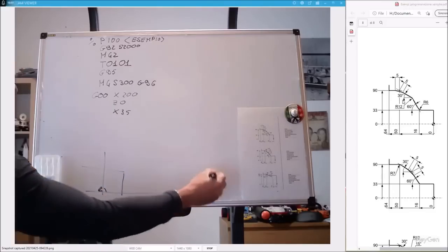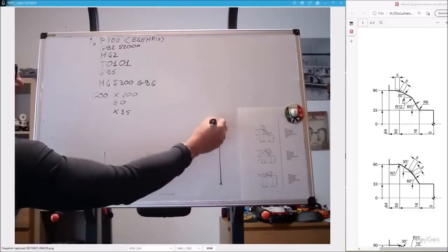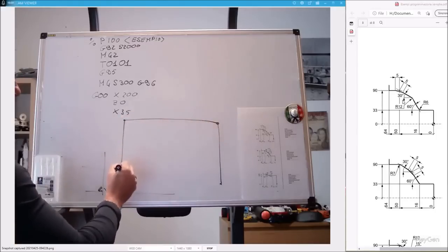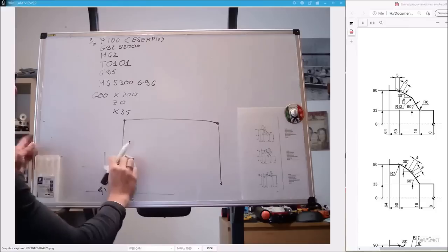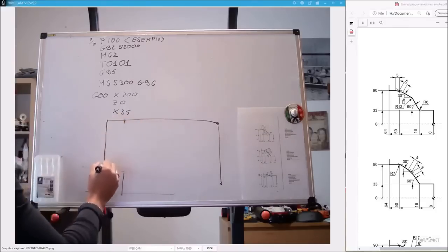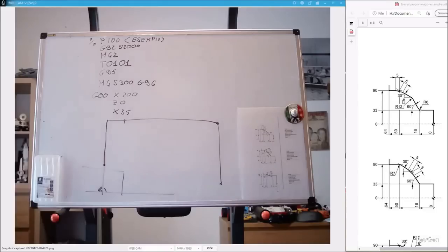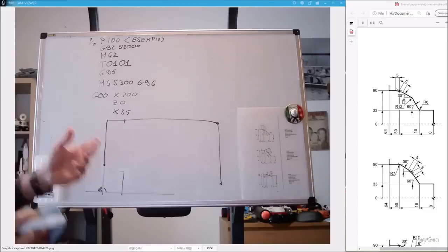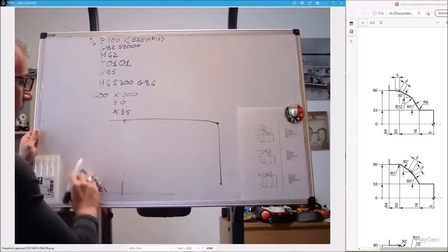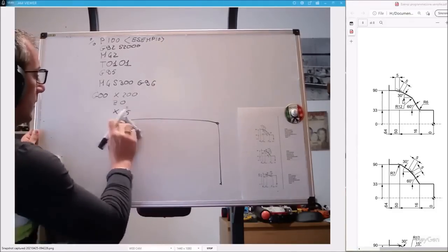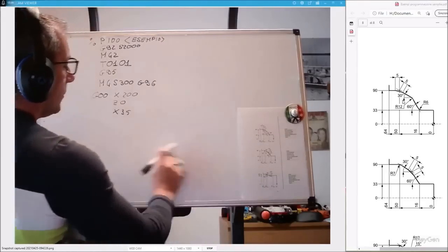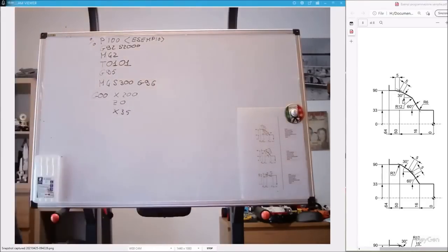What does the machine do? It is here. It raises to X200, moves to Z0, and descends to X35 Z0. Excuse me, it moves to Z0 and descends to X35. I will not have a collision in any way, unless I have machines with particular internal configurations, such as protrusions or obstructions caused by specific equipment. However, that cannot be seen in a course. All that exists in a machine shop.